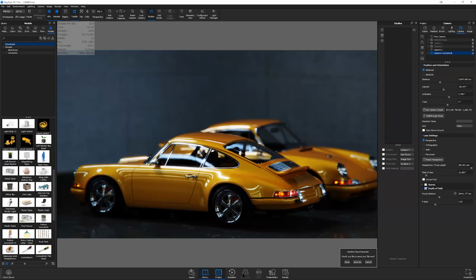the lighting is correct. If you go up to the top next to the light manager and right mouse click there, you should be able to bring up the top ribbon all the way to the right. Yeah, keep going, where it's blank. Then right mouse click and bring up the scripting console. It's kind of hidden, and then you click on that.